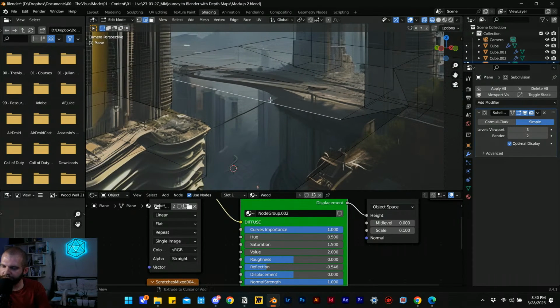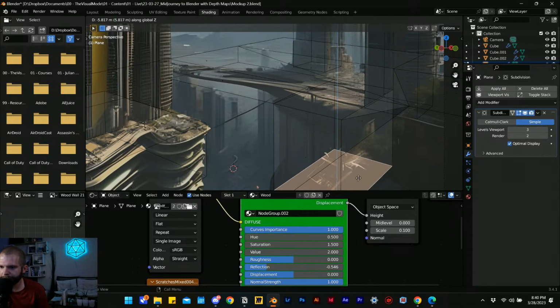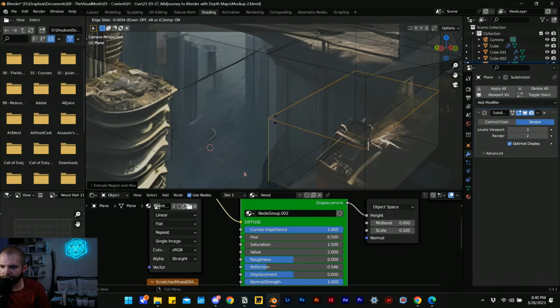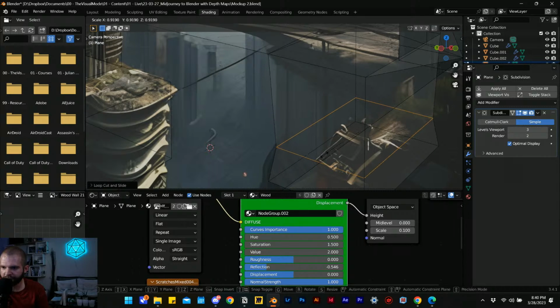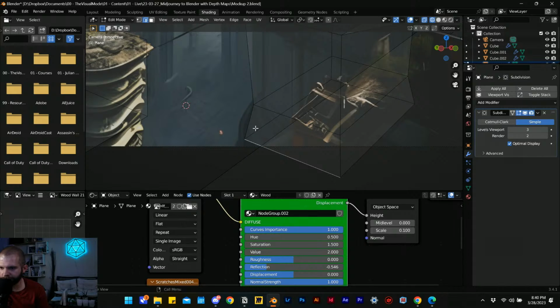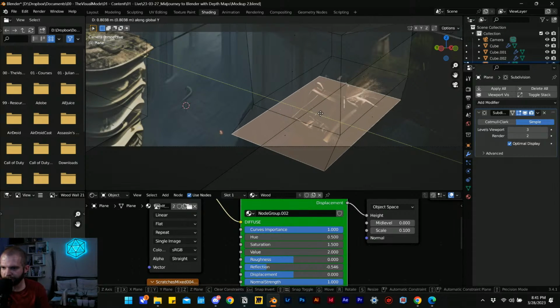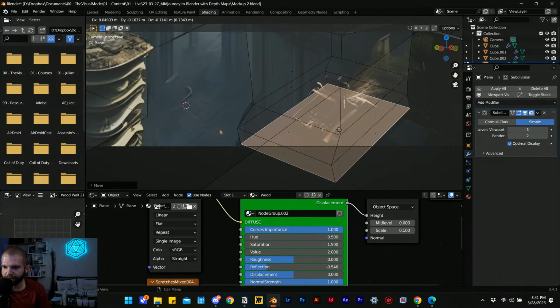We haven't applied the subdivider yet, so we can also use Control R to start adding in some loop cuts, create some more faces like this one, extrude down. And how detailed you get with this, it's totally up to you. I can add a belt there and then scale it in. Alt click could be giving me this whole loop, but it's not. I'll just select that face that I extruded and move that over. Maybe bring it up, match that face as much as possible.